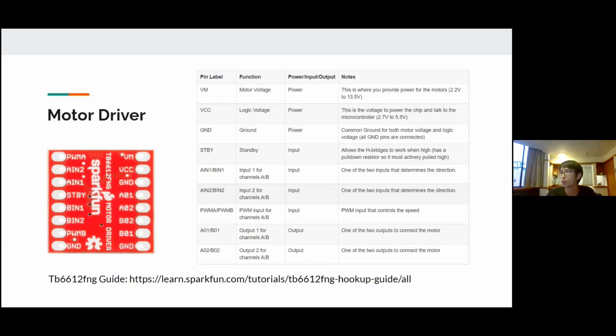That is what your Arduino supplies. So all the other sensors that are connected to the Arduino, for example, the IR sensor, the ultrasonic sensor, they all got VCC, and it's the same VCC. And there is a ground, and the ground is a shared ground. There are 3 ground pins, and they are all the same and connected, so you can use either of them.